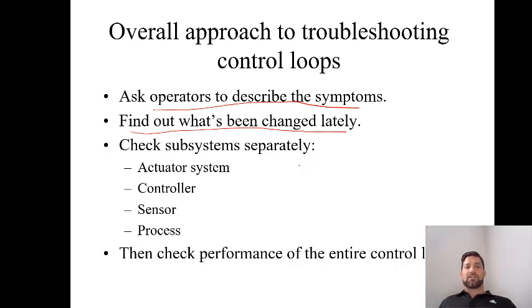That said, I want to point out that oftentimes, if your process is behaving poorly, one thing that people do is they just go right to the controller and retune it. Oftentimes that can get your system working a lot better, but if there's an underlying problem, you can retune the controller and actually mask a problem that's going to limit your overall performance.